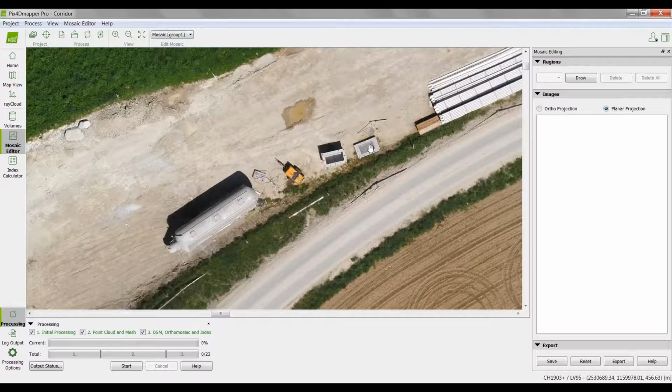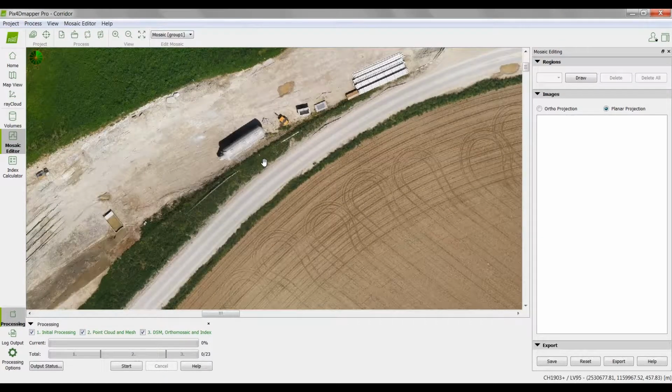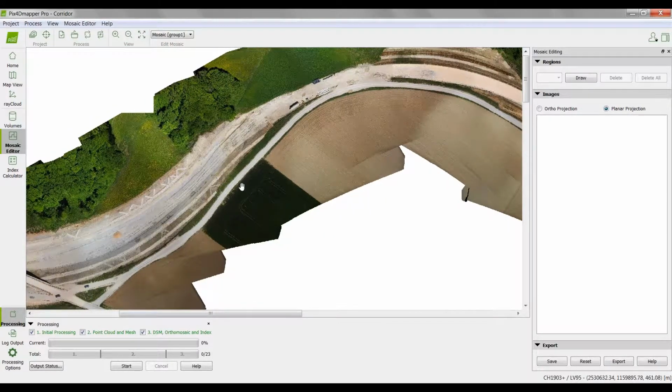So actually just straightforward. And you can do this also with SODA on the normal camera kit or normal integration kit or with a different camera or with Albris even. Just if you don't use any RTK or PPK correction, be aware to lay out some ground control points in order to avoid bending or tilting in the data set, which can happen during the processing because of the narrowness of the project.